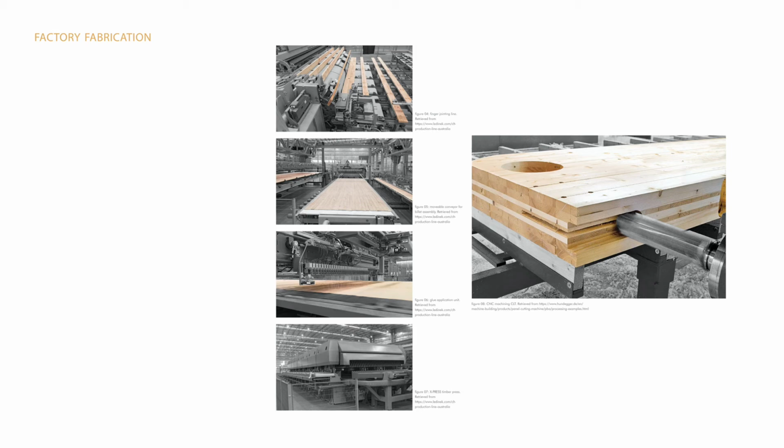As the connections designed in this research use timber and are intended to be used for CLT panels, the fact that the waste timber is treated is irrelevant for this project, and therefore can be used to create the keys. This allows for the manufacture of the keys to take place in the factory using existing tools and creating a much smoother process and reducing waste.